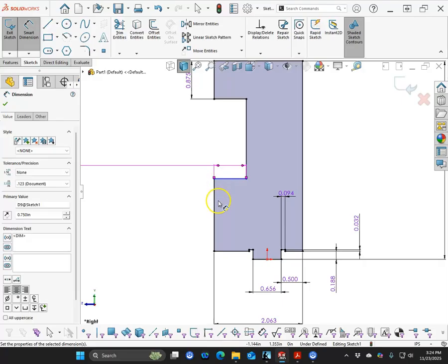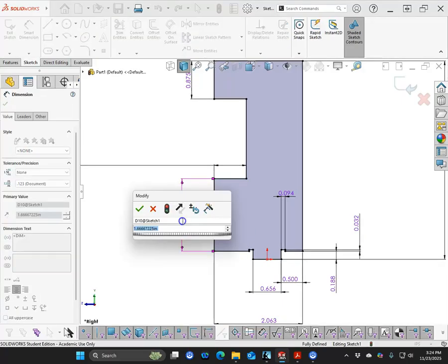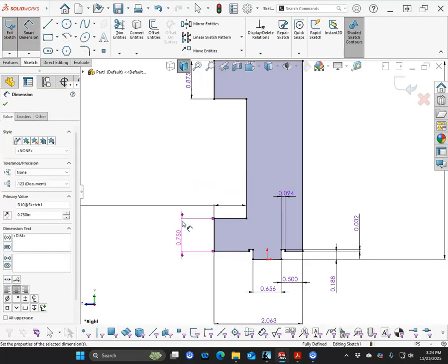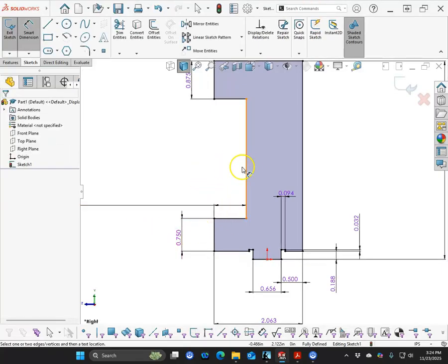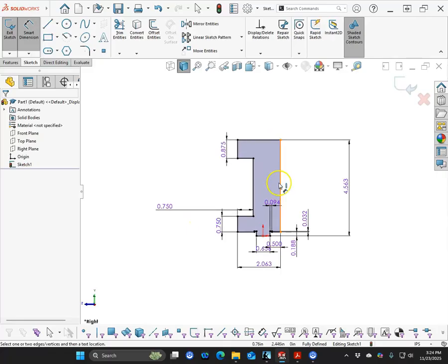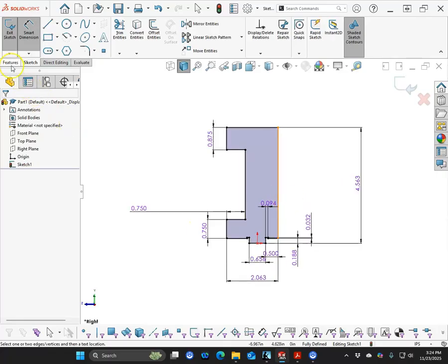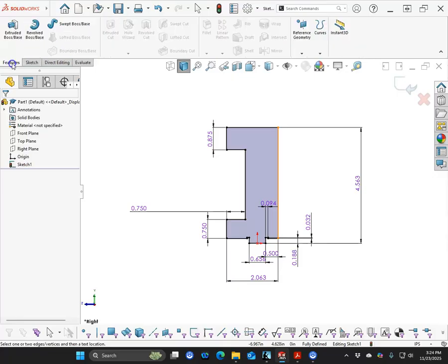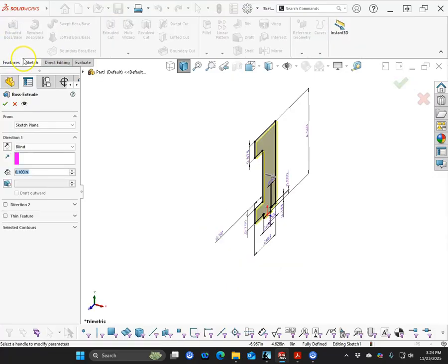All right, so I said I was going to try to cut away the angle. I'm probably just going to have to add the angle back in. So since the number is kind of in the lower left, we'll just fill this back in with that 20-degree angle. All right, I think I've got enough geometry. We'll go ahead and extrude to the midplane.